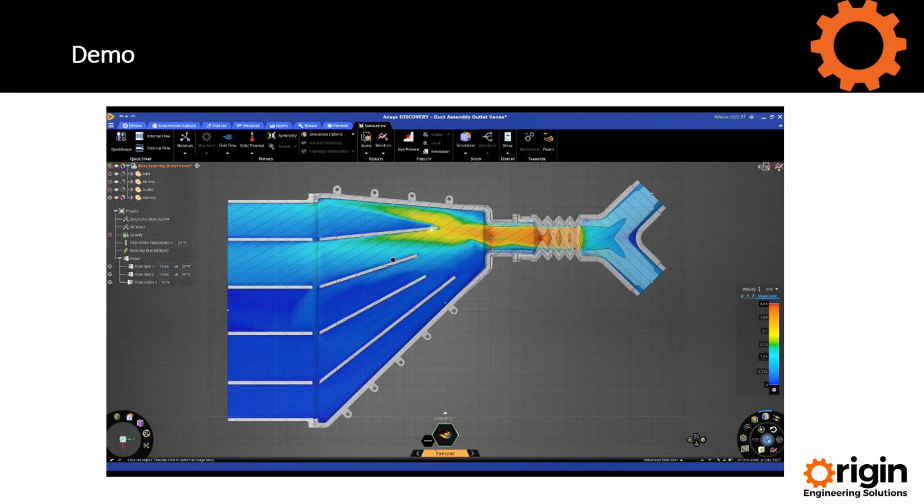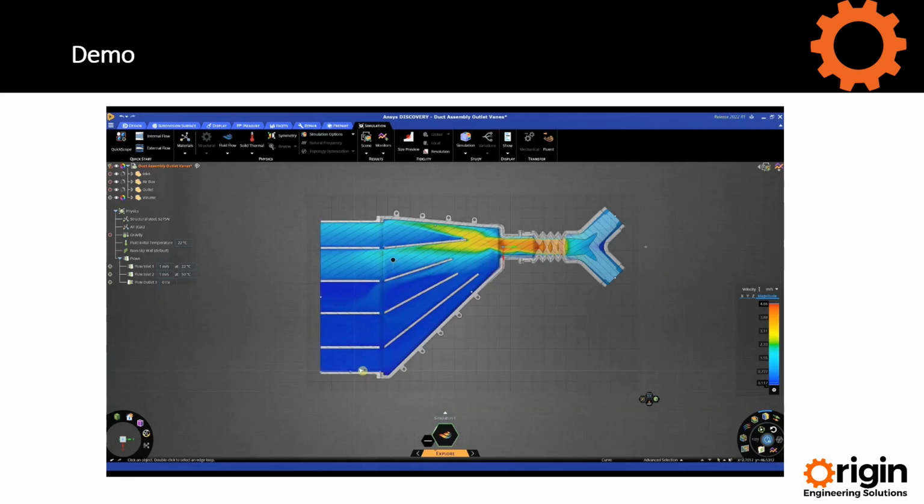We can change the size of these ribs. We can maybe add new geometry to direct this flow more, maybe down towards these last outlets. But you're doing that on the fly. And again, like we did with the structural, if you want to take this into the Refine mode or even transfer it to Fluent, you can do this in Ansys Discovery.